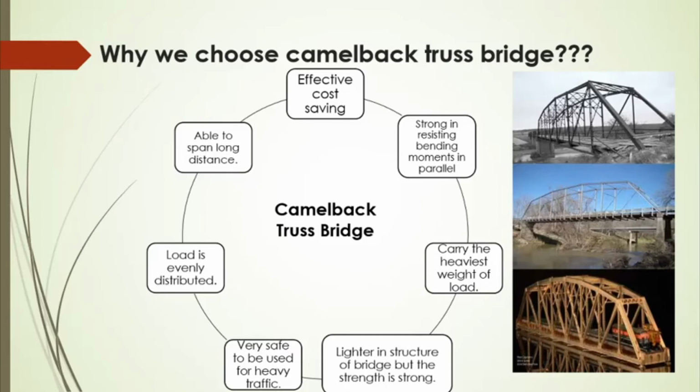The bridge narrows down near the piers or ends of the span so that it is strongest only where it needs to be, and cost and materials are minimized as compared to a truss having a constant height, which by necessity has more strength than needed in the ends approaching the piers.